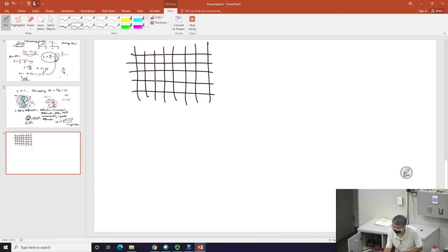You could have a pre-made melt, and then you start to introduce peroxide or whatever cross-linking mechanism you have, and you then start to fix them. And abstractly, one can denote them as I just drew. Now, your whole sample is a giant single molecule because everywhere is chemically connected. And of course, this is 3D. I could only draw 2D for you.